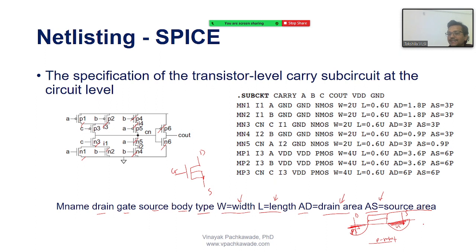So you can see now this kind of circuit description actually helps us in describing the physics of a transistor and hence the physics of a circuit. So you have accurate and very much detail of how the circuit is behaving, and because of that we would be able to calculate all the parasitics. What are the parasitics in this circuit? Parasitics are, I told you, the capacitances inherent or already there with the circuit.